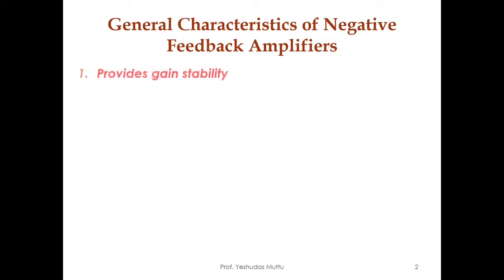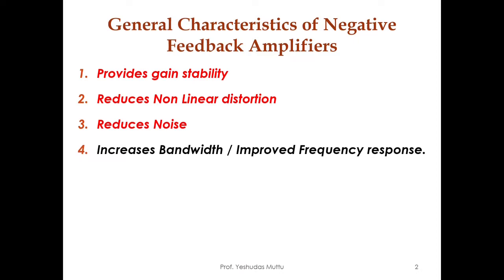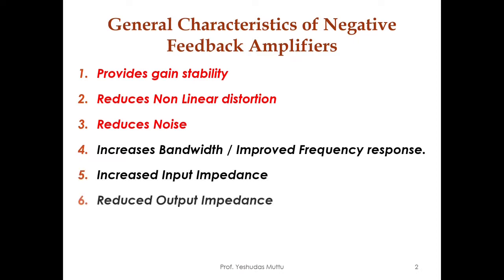The first one is gain stability, then nonlinear distortion, noise, increased bandwidth, increased input impedance and reduced output impedance. The first three, that is provides gain stability, reduces nonlinear distortion and reduces noise. These characteristics of negative feedback amplifier we are going to study in this particular lecture video.